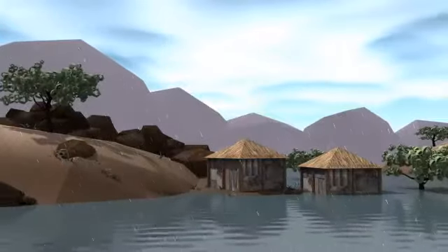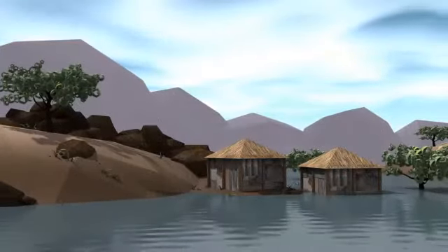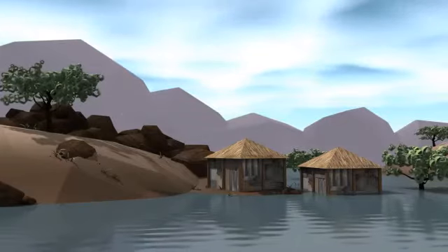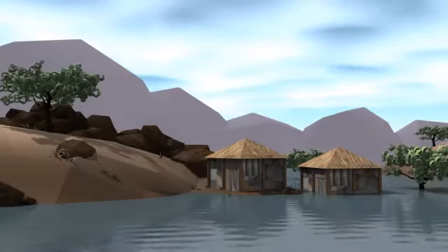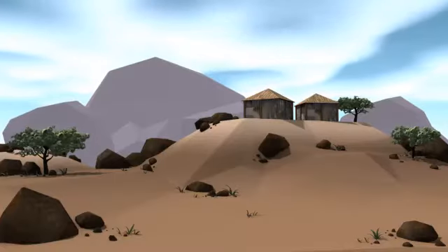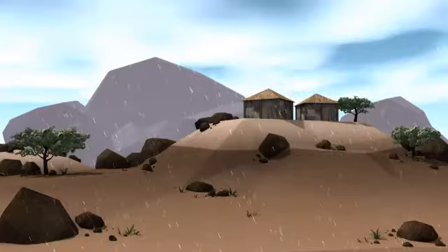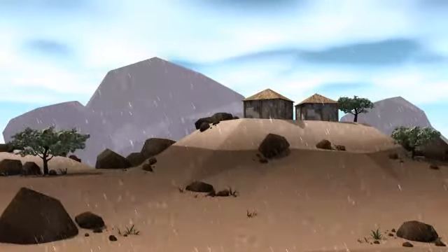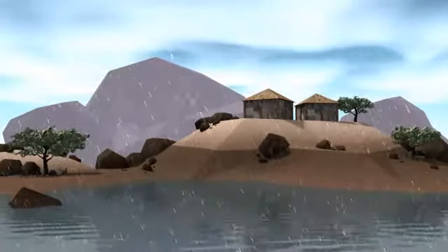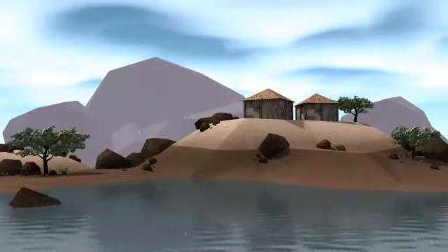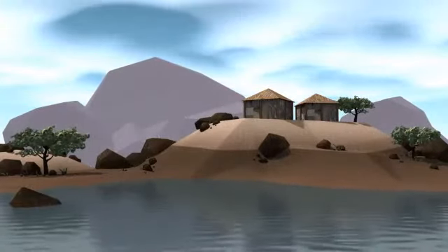Shelters located in these areas are at risk of damage or destruction if water levels of the river rise to cause flooding. To minimize the risks, it is advisable to build on higher ground. It is important to know the approximate water levels in times of flooding to use as guidance. Previous floods can help you identify the level of risks. The shelters can then be located on higher ground at a safe distance from the traditional floodplains.